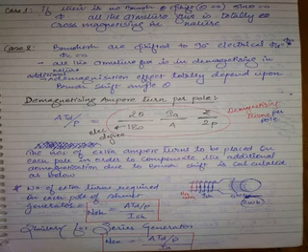Let's be very clear. We will say everything in electrical degrees. No concept of any mechanical degrees here. If you refer one book, it will be mechanical; if you refer another book, it will be in electrical degrees. You just standardize everything into electrical degrees only, because the basic heading is per pole. Under a pole, how many electrical degrees? 180. Always 180. Let there be 2 poles.